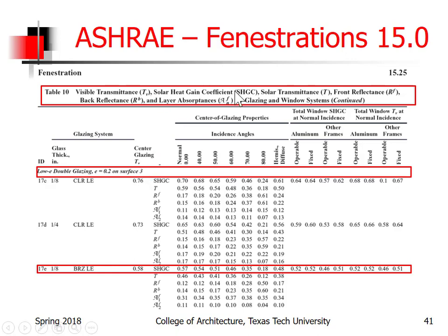The solar heat gain coefficient makes a difference whether it's on 2 or 3. And 3 means it's going to reflect or emit energy to the exterior of the building. If it's on a 2, it's going to emit energy into the building. Okay, and so if we look, the next thing we're going to do is determine the thickness of the glass itself. Is it 1/8 inch thick or is it 1/4 inch thick? And of course, the thicker glass is usually used in much larger windows. If you've got a 10 by 5 double pane window, then you're going to need thicker glass than that to withstand the winds and stuff.